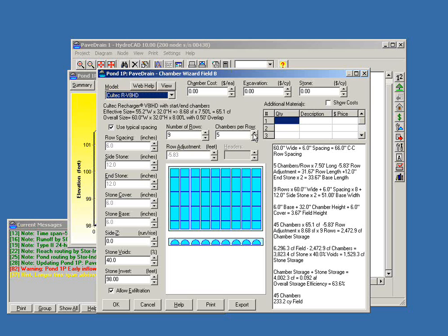What we've experienced on some of our parking lots, which has been going over 2 years now, is that they have not had to have any maintenance. Obviously every site is going to be specific, but with the open joint concept that we do with Pavedrain, we don't backfill our joints with smaller stone chips or a sand layer. It allows the fines to work their way right down through those joints and into the larger stone bedding layer that's below Pavedrain.